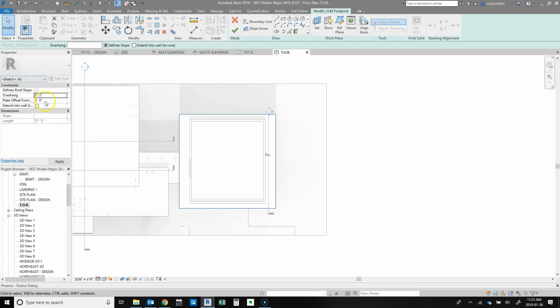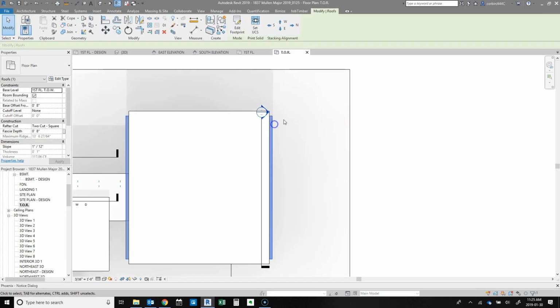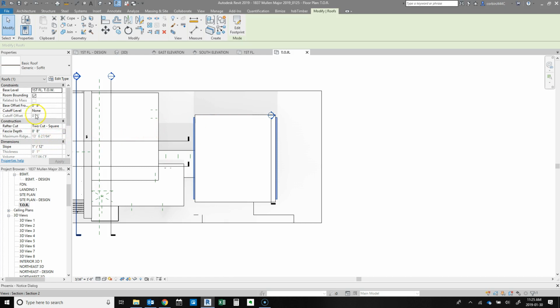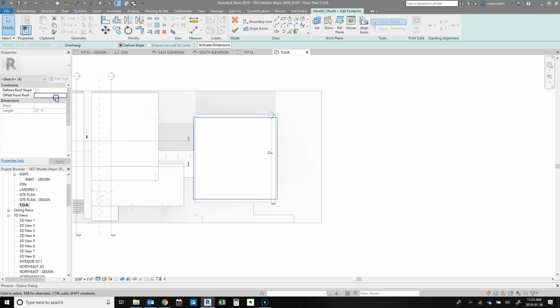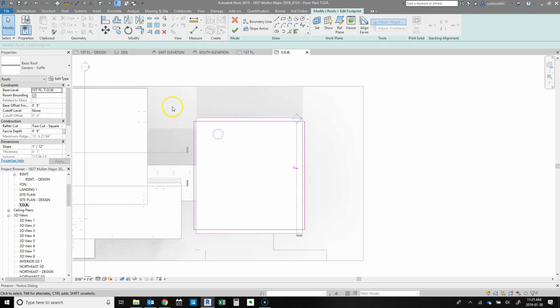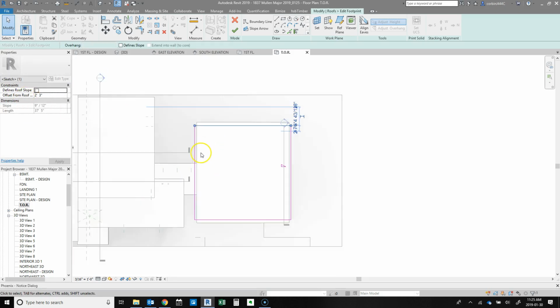And the reason why it's 3.3 is our township here only allows an overhang of 3.3 inches. So that's kind of a local condition. Otherwise, that overhang would then be considered as part of coverage. Do the same thing with this, but instead of doing 3.3, we're actually going to do 2.3, just so that the fascia actually steps in a foot. Sorry, I hit the wrong number there.